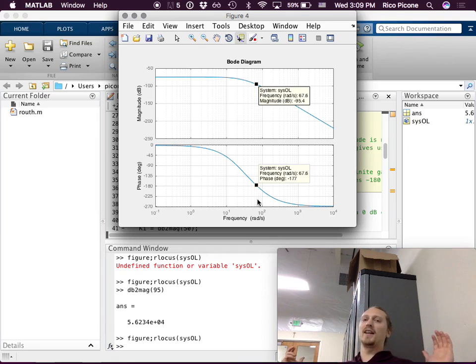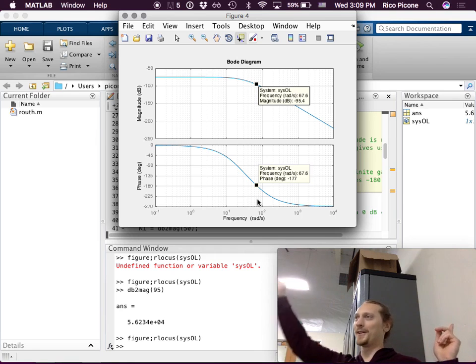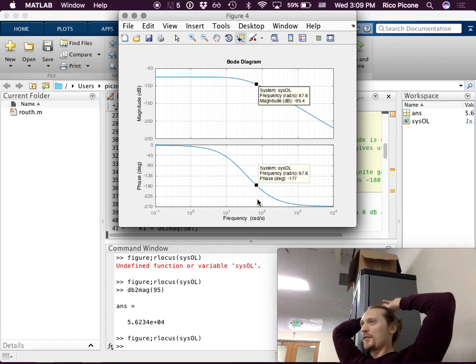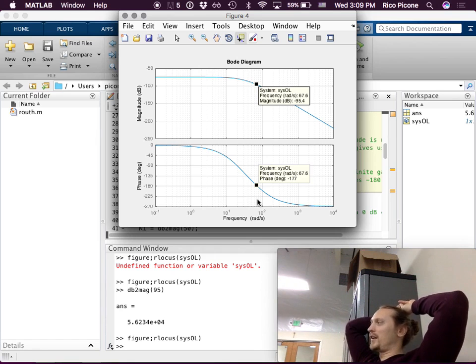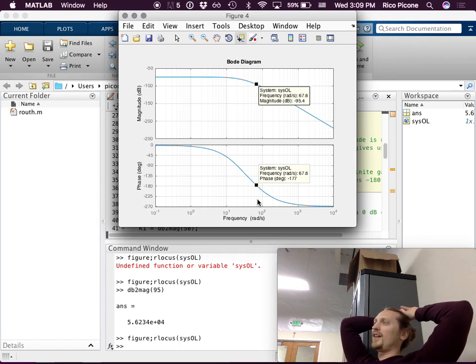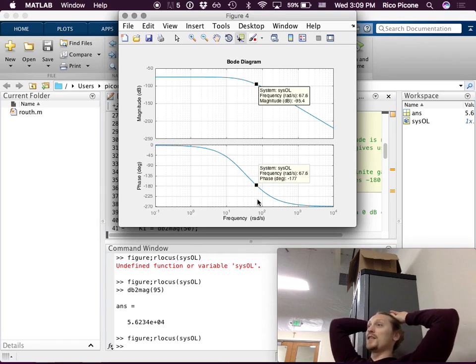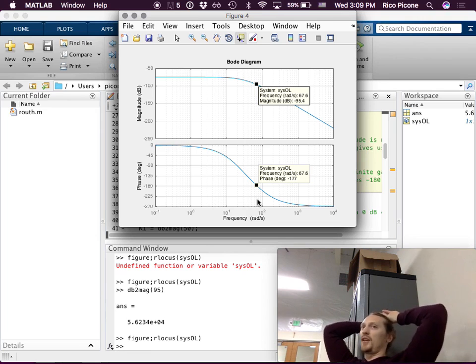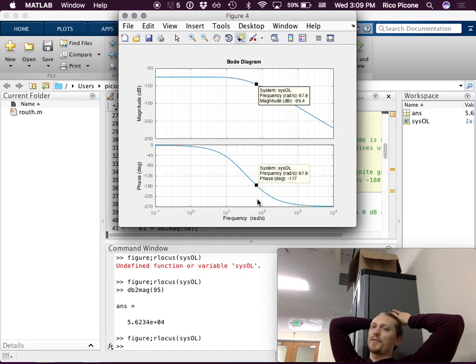With the Bode plot, you look at it, it doesn't leap out at you that there's a certain gain at which this system goes unstable. It does when you look at the root locus plot, right? It's like, oh, clearly this goes unstable. The information is in there. It's sort of just more hidden. Same with the Nyquist. It's more obvious in the Nyquist than it is in the Bode that it goes unstable, because the encirclements thing is pretty easy to see. But the Bode is easier to work with for designing how much to increase the gain and all that. So that's why we work with the Bode plot.